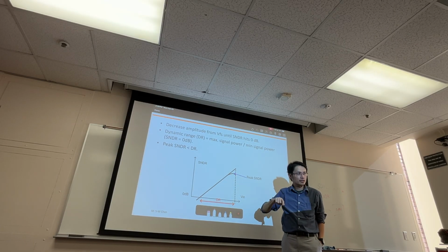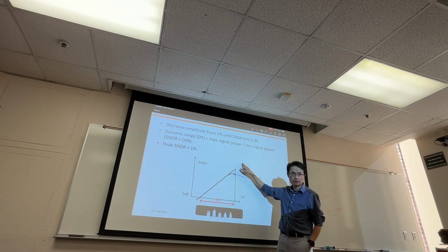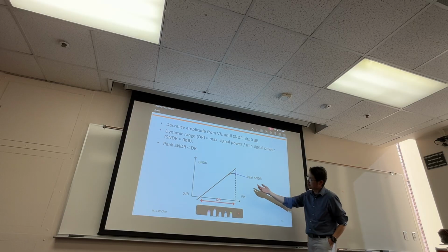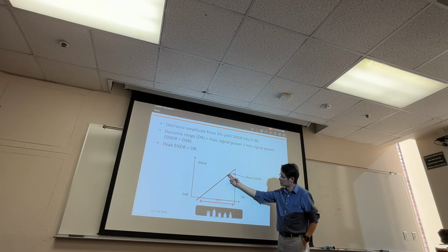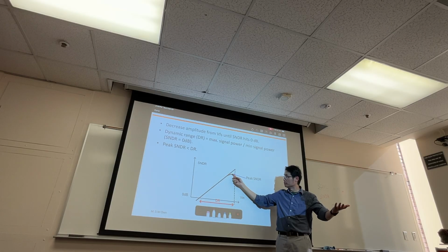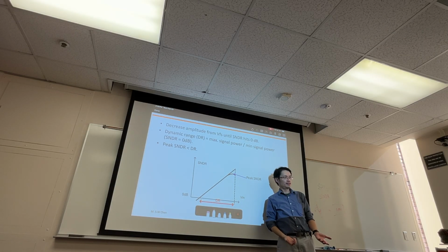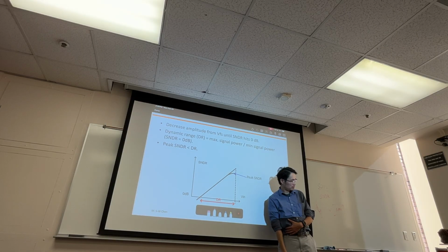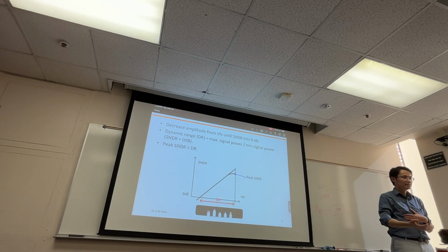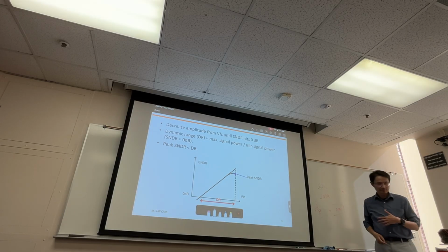What's going on there? Shouldn't that keep going higher and higher? Why is it that you see it first slow down, and then become flat, and then actually it can go down? Your SNDR would become worse. What's going on here? Distortion, because you go above full scale.